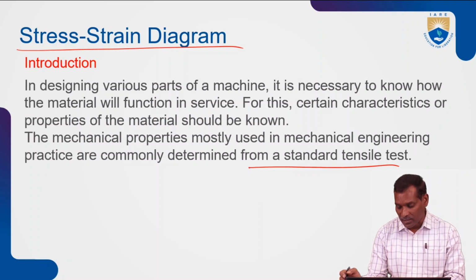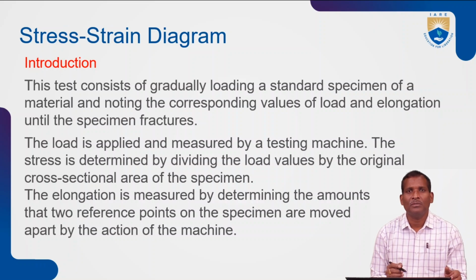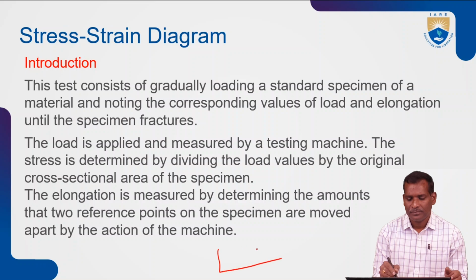What is this tensile test? This test consists of gradually loading a standard specimen of a material and noting the corresponding values of load and elongation until the specimen fractures. So take the standard specimen.